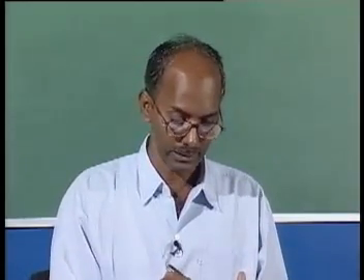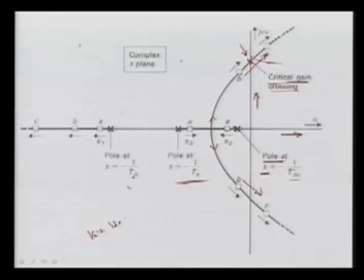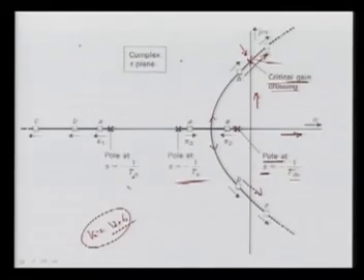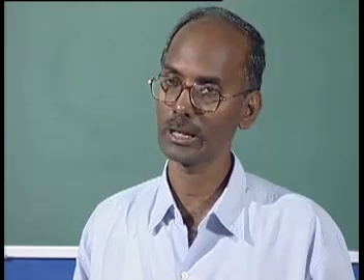And we find that the gain was very less, 12.6, which is very less. For this, your steady state error will be very high. Because we require more static gain, we have to do some compensation, and then we can improve the stability of the loop. Let us see the various ways to improve. We observe that stability and accuracy are conflicting, hence for both we use the compensator. It means we can improve the accuracy by going for higher gain, and at the same time improve the stability of the loop.